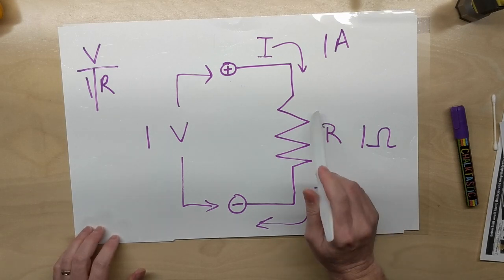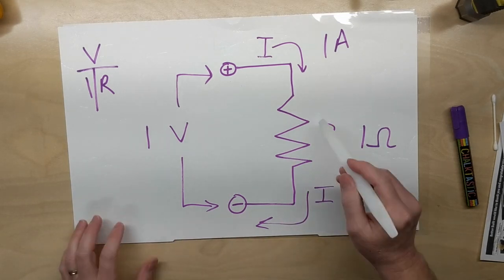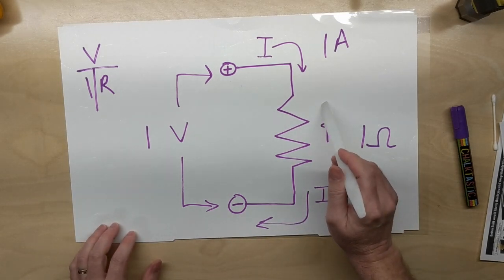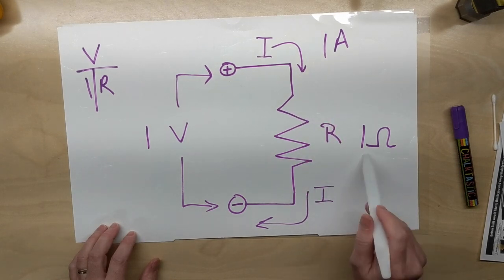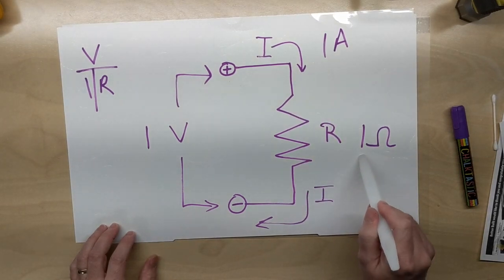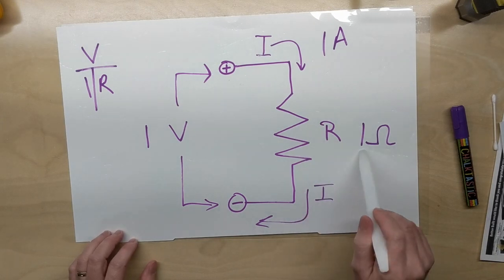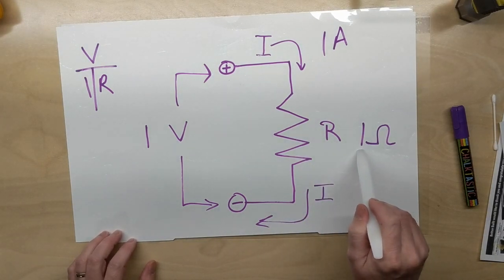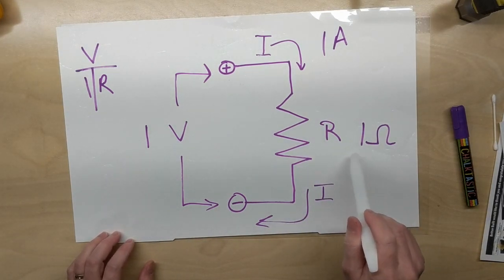So just think about that in the future, that there's ways to check current by reading voltage if you know the resistance of what you're reading across. It's not uncommon at all to see a very low ohm resistor across a circuit for current feedback.